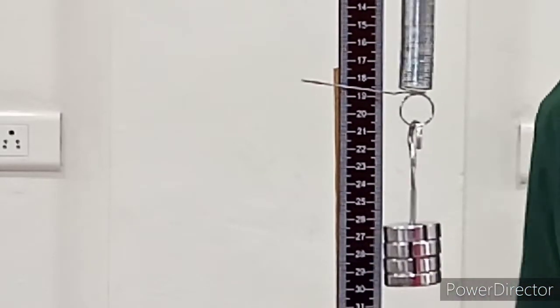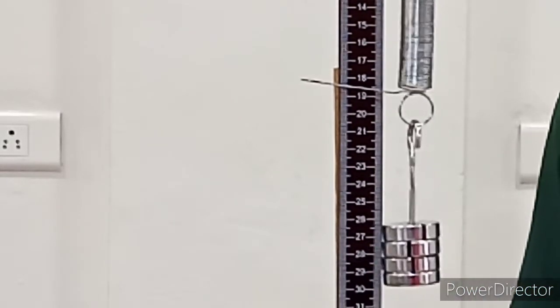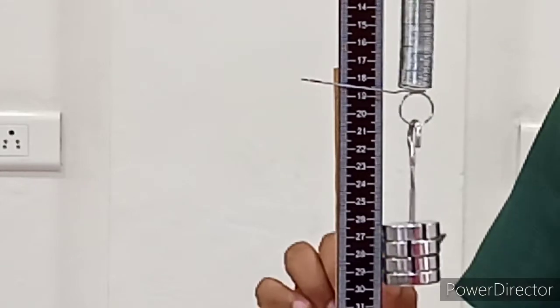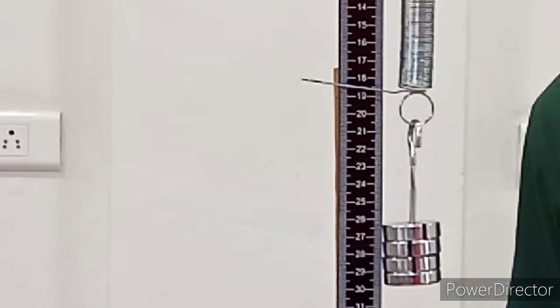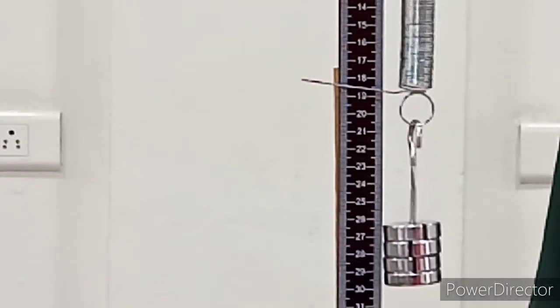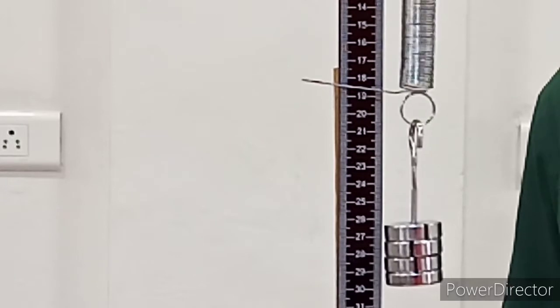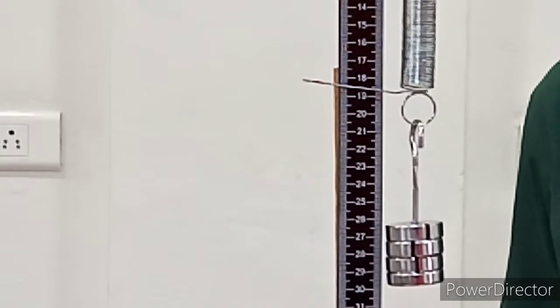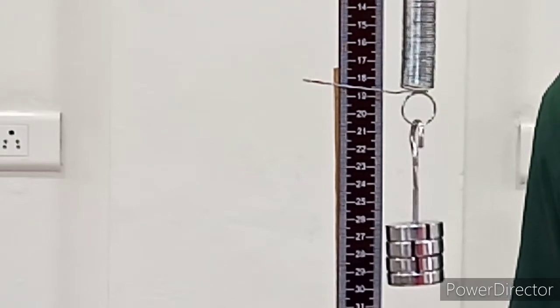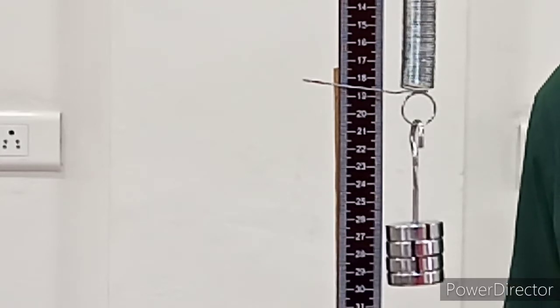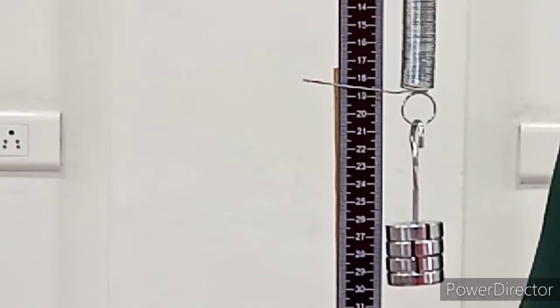So another 50 gram weight is detached, so that now what is remaining in that hook is dead load plus 150. Therefore, across 150 gram weight, I am noting down it is found again 18.9. While loading also it was 18.9. While unloading also I find it to be 18.9. Suppose if it is other than 18.9, you note it down, no problem, because we are going to take the average of the extension produced during loading and unloading.